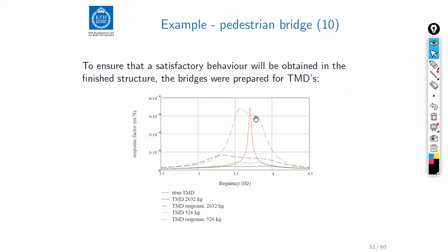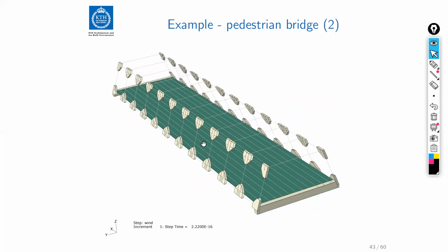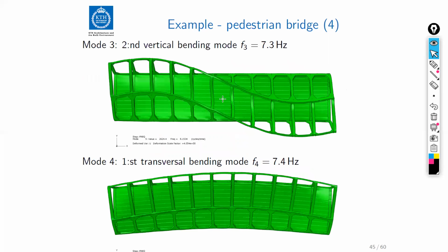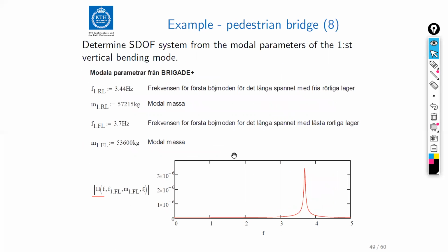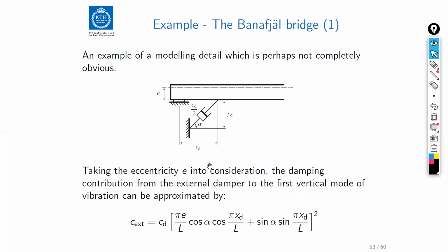At the same time, the capacity to reduce the vibrations is somewhat smaller, and the motion of the TMD becomes much larger. So maybe this TMD motion would be difficult to fit. If you remember what the structure looks like, the only place we can put the TMD here is underneath the bridge. And there we have about 400 millimeters of vertical space. But it is not a problem to design both of these TMDs that I suggested here for that purpose.